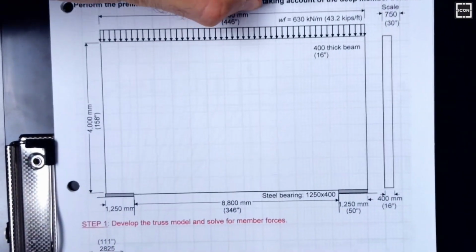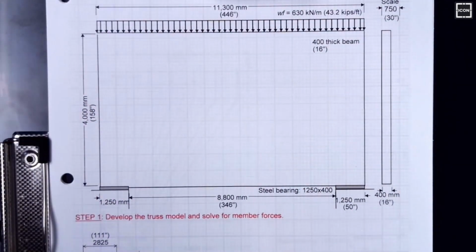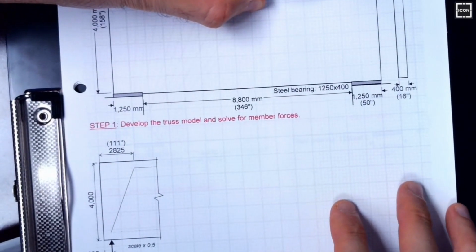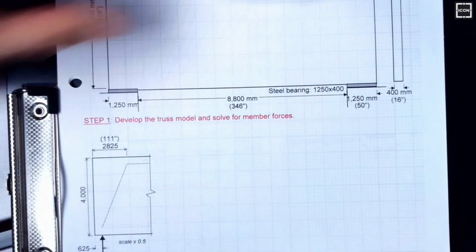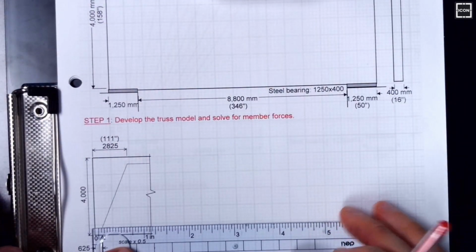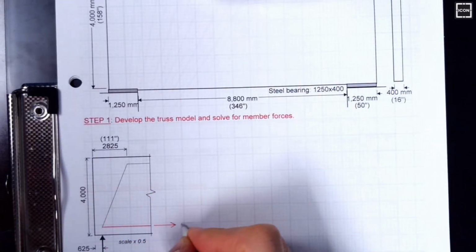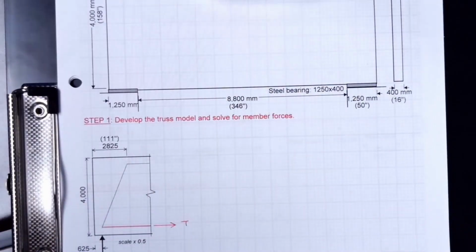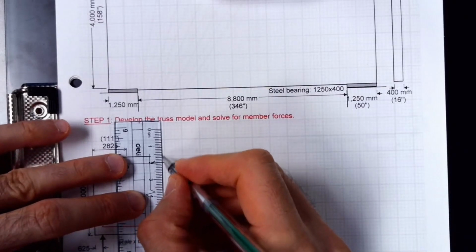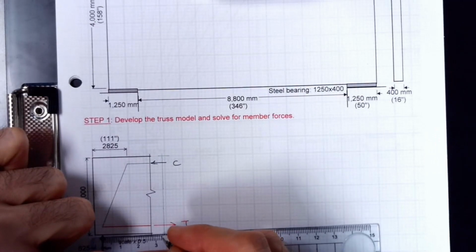So the first step, as always, is to develop the truss model. And for this, we again need to sketch two lines, one horizontal, other one vertical. One is going to be strut, the other one is going to be tie. We know from the previous example it's going to be something like that. This is going to be tension, top would be compression. Again, we need distances. You can start by assuming anything, but of course a good assumption will minimize the work.